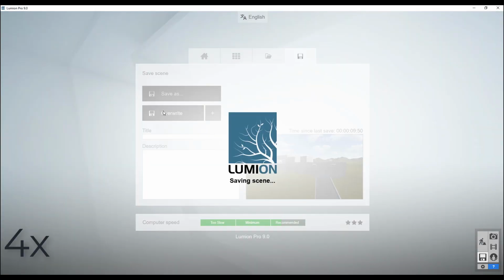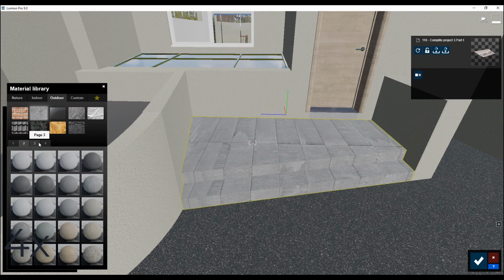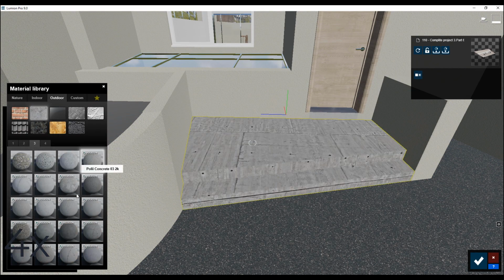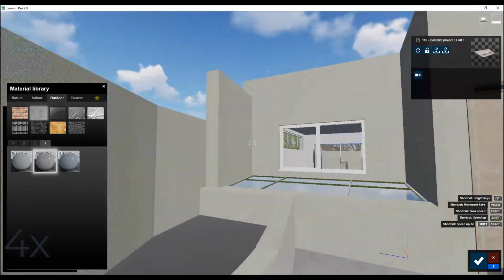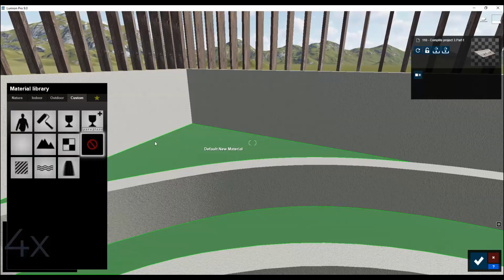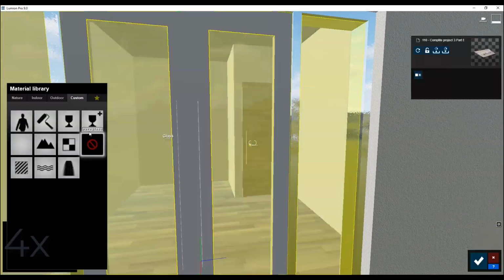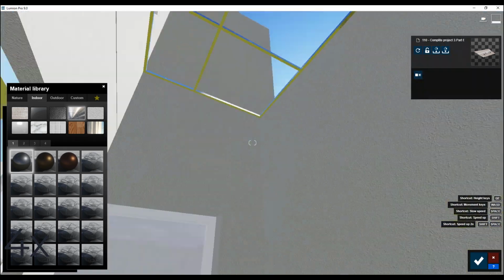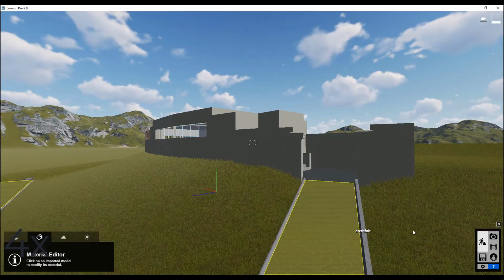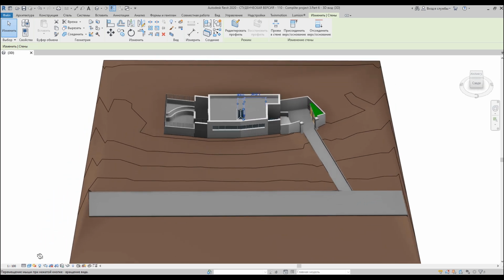So if you can, just try to separate your floor, your roof, and your road. It should be 3 different types of floor family. Let's see how it looks around. Everything should be alright. Here I'm just applying some aluminum for my curtain wall, because it's a different material, and that's it. And in 20 minutes we already finished our model. Actually not, we spent like 1.5 hours.